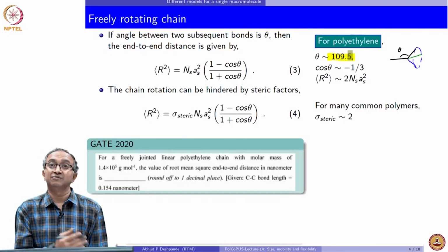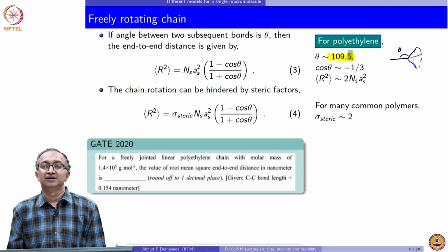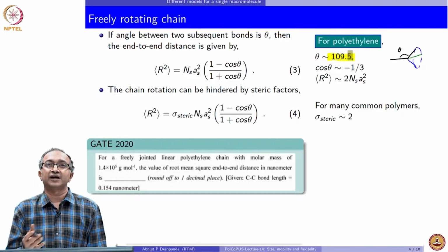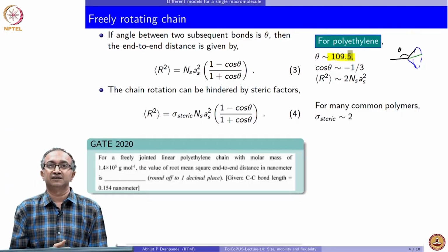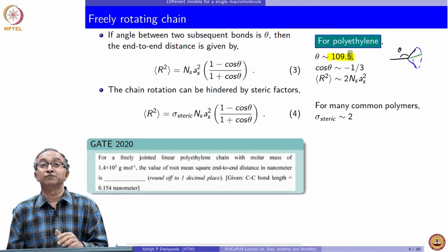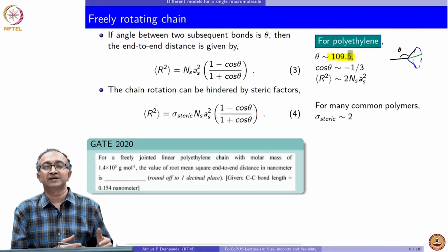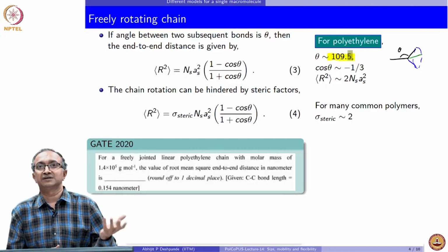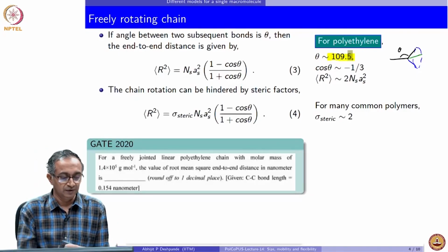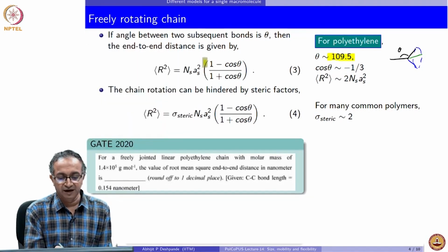And therefore, single macromolecular behavior becomes a very good description of the overall bulk behavior of the polymer. With the presence and absence of different types of groups and how they interact with each other, we can find out how easy or difficult the conformational change is. Therefore, we can find out the statistical properties of a single macromolecule, and once we know that, we can also say many things about the bulk response of the polymer.